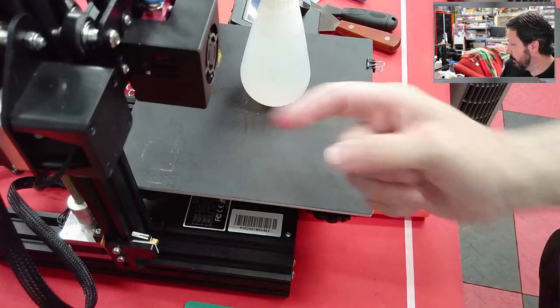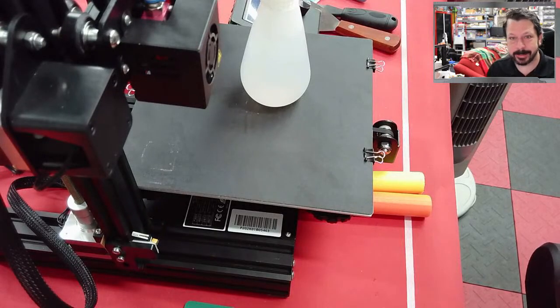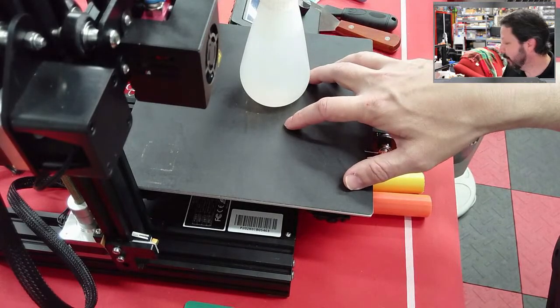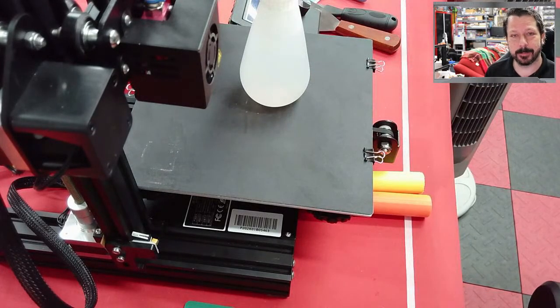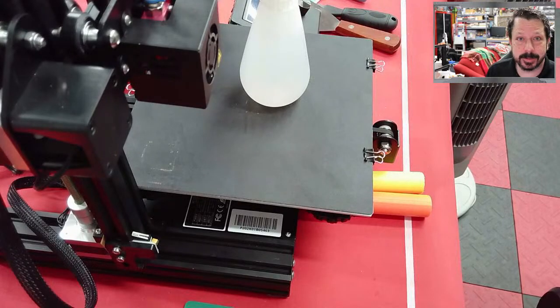And if you get the distance between the nozzle and the bed correct, so that you're laying down a very good first layer, almost all materials will stick to glass, pure glass. You can get a picture from Walmart and cut the picture frame out, put the glass on here, and print on it. Just be careful, because most of the time when you cut it yourself with one of those glass cutters, it's going to have a little bit sharp edge. You can sand glass with some sandpaper. You can sand that edge down a little bit.